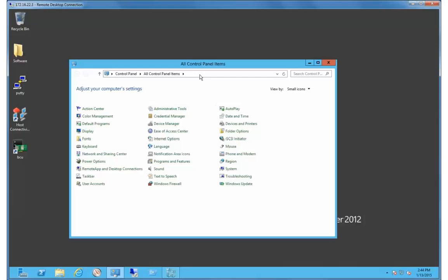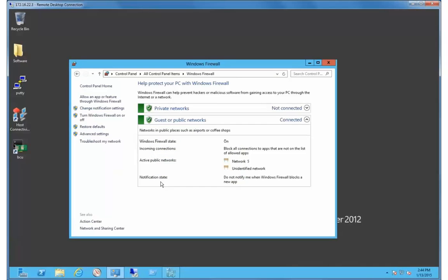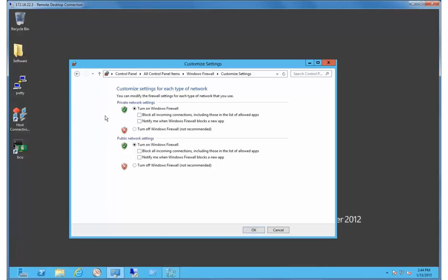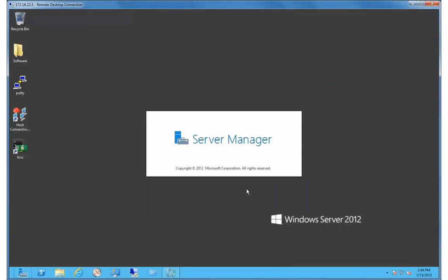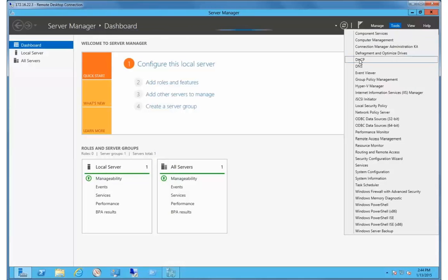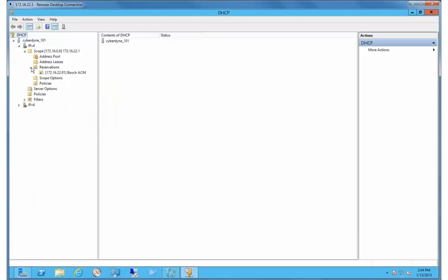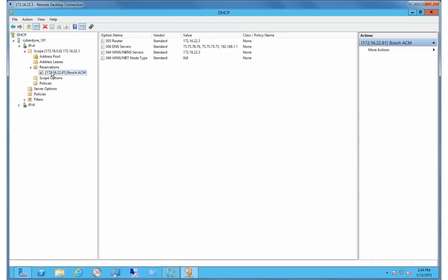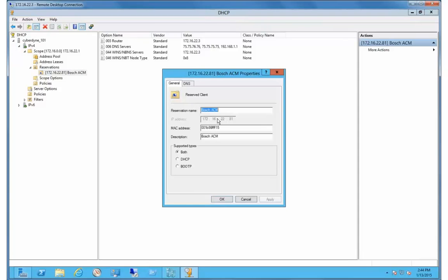To support the connection between Bosch APE and XProtect, you will want to either disable the firewall on both of the target servers, or you can create custom rules to open the virtual ports required for the integration, 808 and 809. In addition to this, you will need to have a DHCP server in the network to provide an address for the Bosch Access Modular Controller hardware unit, which requires DHCP to provide an IP address.